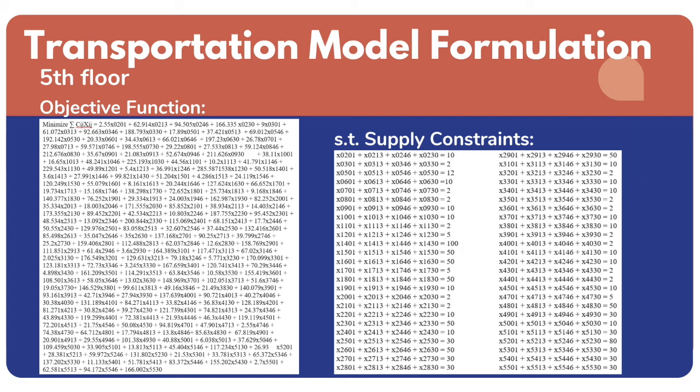This slide also shows the number of occupants per room constraints, or the supply constraints per room. For example, let's consider the number of occupants for room number 2. This constraint represents the number of occupants transported from room 2 to all 4 exit stairs. The number of occupants transported from room 2 is then limited to the 10 people present inside that room.